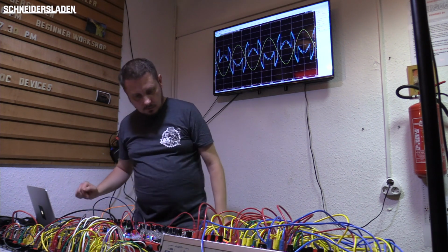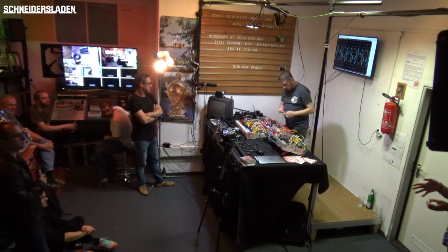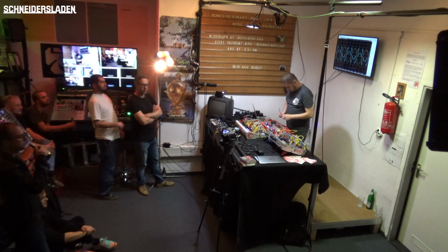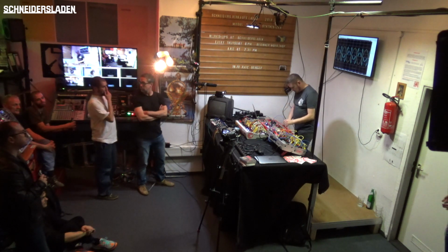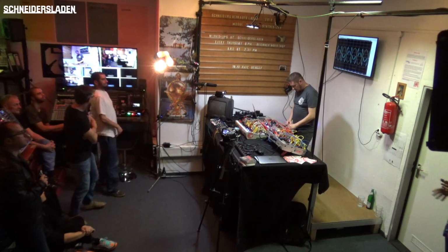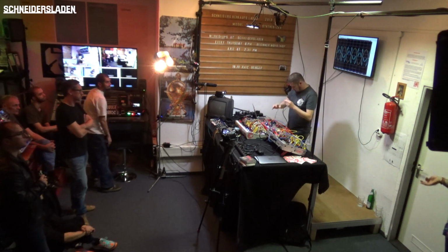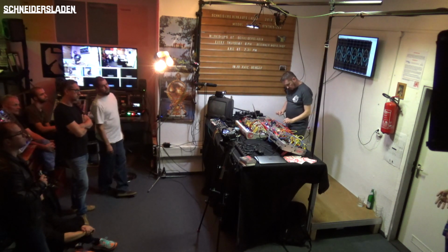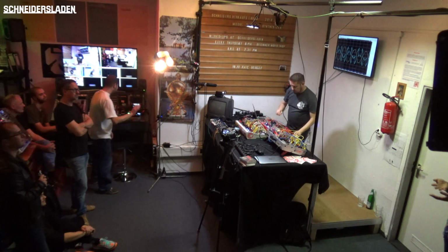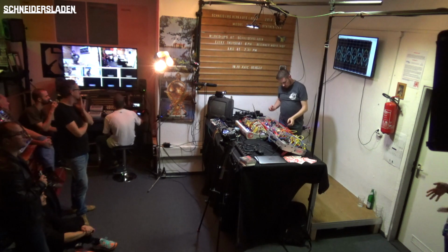So it is really something different than processing just an analog signal, and it gives you lots of possibilities. You can do some processing with 8 different signals, but it's still just the gate, so just switching some of these gate signals on and off will give you very interesting effects. It's really a cheap kind of processing, because you don't need to use complex modules for this.